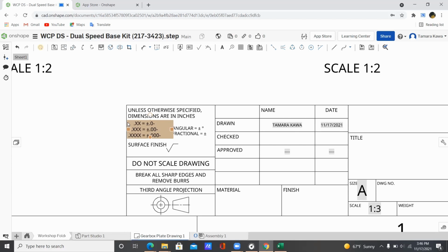So again, the reason this might not have come up is because a lot of times teams will just say, okay, if there's a dimension, it'll be to this plus or minus. And that's what these are. So if it's to 2 decimal places, it'll be plus minus 0.05, let's say. Or if it's to 3 decimal places, it'll be plus minus 0.02 or something. So it's like how much method space. Exactly. Like space when you're sewing and you give yourself seam allowance. Exactly. That's a really good analogy.